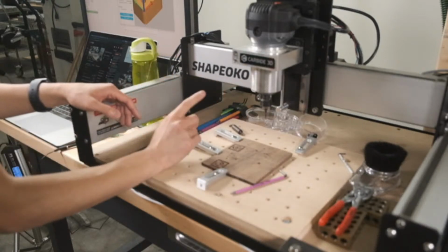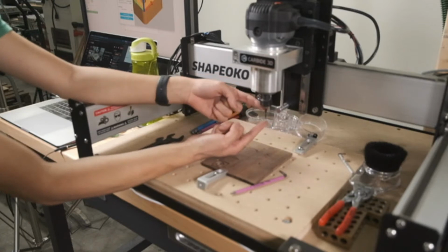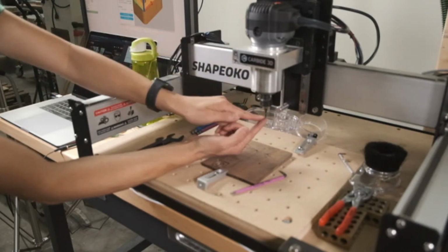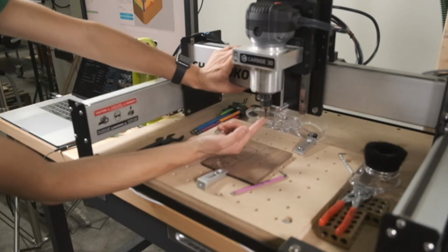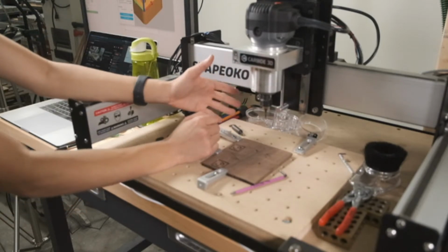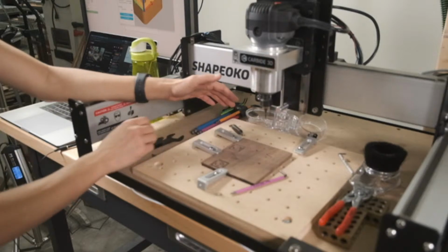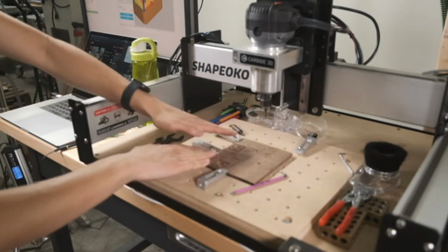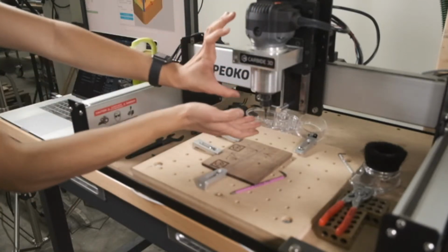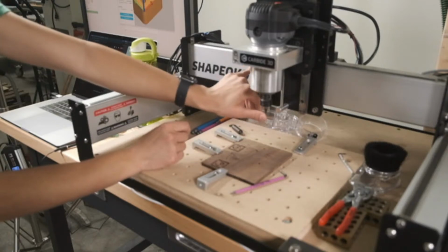The other thing to keep in mind is that the shorter the distance from the cutting tool to the mount and from the cutting tool to the rail, the less torque you have acting on the system. People always like to keep their baseboard clean and have as much clearance as possible, but that means you have to lower your router down a ton, and so the moment arm between here and the rail is higher.